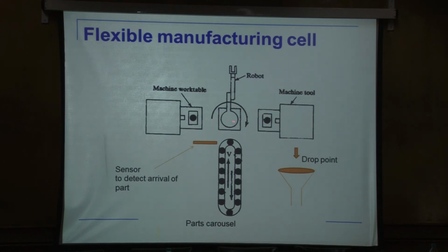Now in this there is a sequence of operation, plus there are times of machining. Okay. So we have to sequence those times now. Otherwise what will happen is they will end up with a deadlock now. So if this is doing machining, that is doing machining, and the robot also picks up one part from here. Now it has no way it can pick that up and pick that up also. Okay. So when there is multiple machines, multiple times involved, then it becomes difficult to sequence. Okay. And that is where the real challenge in programming is. And that is also why it is so expensive.